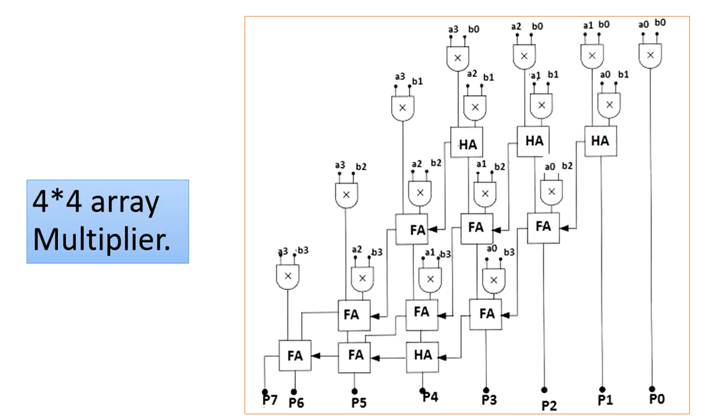The maximum range of this product will be 7x7, that is 49, and this can be accommodated in 6 bits, which is the size of the output product. Here we will have 3 partial products which can be added using 2 methods. Either you can add the partial products using 3-bit full adders, or you can make use of individual single-bit adders.